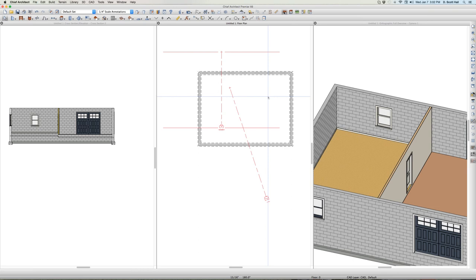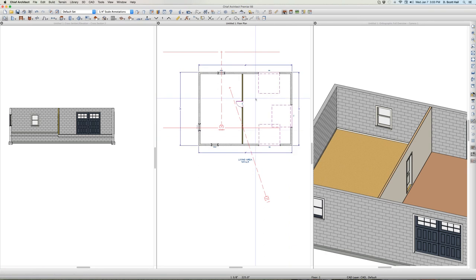But what's happened now is this footing, I think, has defaulted to the default height. And that's okay. But maybe I want to control it separately. Maybe I have 2 or 3 rooms or houses side by side, and I want to control each one separately. So I cannot rely on the default, because suppose I have 2 buildings, each building might have a different height. So I want to be able to control it. So I'm going to have to come back and eventually make that a room depth so I can control this height. But as long as it's not a room depth, here's the secret.